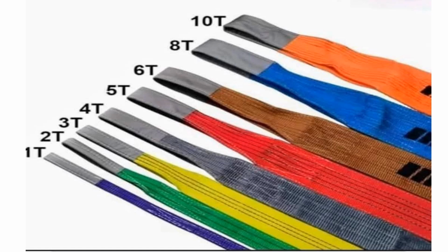You can know another thing also. You see the yellow color where my pointer is. This area has 3 stitching, which means this is a 3 ton sling. You see the green color web sling here, with 2 stitching. The green color stitching is inbuilt there. This is a 2 ton web sling. In the same way, in every sling we have the stitching inside. You see here, 5 stitching is there. This one is a 5 ton web sling. So we have to know the load, how much it is, and the shape, to decide which capacity of sling to use.